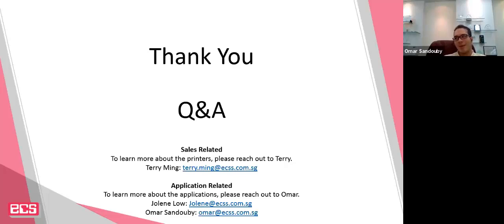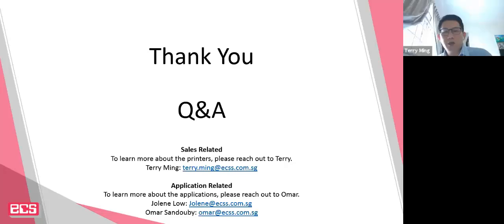Again, with this kind of accuracy, it's worth highlighting that other SLA technologies use a very fine laser, but the fact that you're still building in an open tank and relying on supports would, unfortunately, give more deformation to your part, especially if the part has thick cross sections or longer features that are not very well supported. But material jetting, because it's more like plug and play and the support structure makes sure the part is fully supported, gives you better accuracy in that regard as well. So yeah.